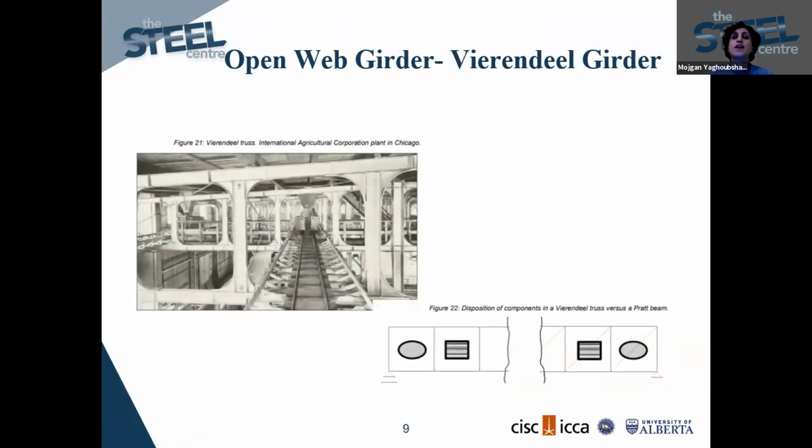And also this type of truss, which can also be used in the ceiling, and they call it a Vierendeel girder, is very popular because it provides such easy access and such wide openings to run through all the mechanical piping and plumbing. And also, if you look at this industrial building, they were able to run a pathway through the ceiling of the building.